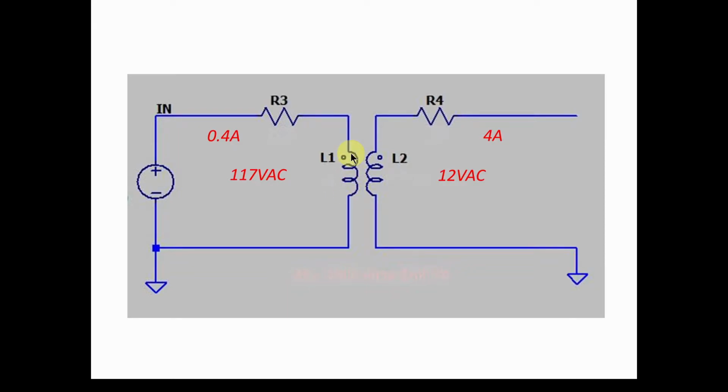So we know that if I apply 120 volts to this winding and this secondary is open, there's no load, I don't expect a lot of current to flow, all right? This thing is rated 0.4 amps normal load current. So if this has got 4 amps of load current, we're going to see 0.4 here. So that tells you the current I expect with this with no load, with this opened, should be nowhere near as much as 0.4 amps, right?